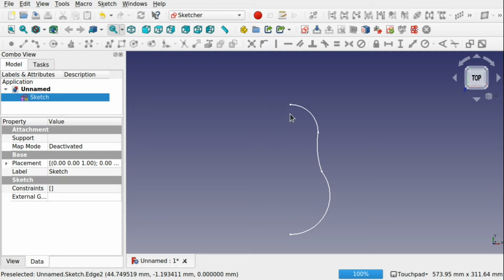I'm going to create another object in here. Now there's two ways that I can tackle this. We can tackle this by placing a single extruded vertex in the center here and curving out from this vertex to the sides, or we could place a line across here with a number of vertices going up and curving lines out to create the profiles. Either way, we're going to use both the blend tool and the discretize tool over in the Curves Workbench.